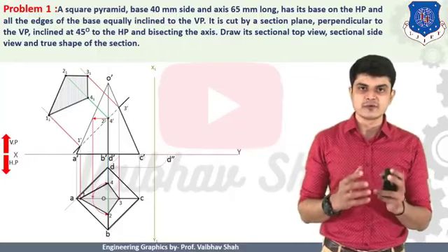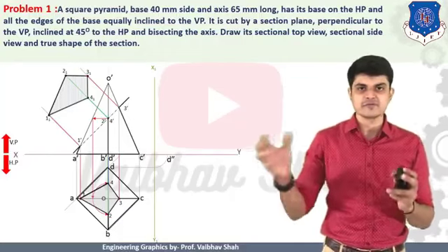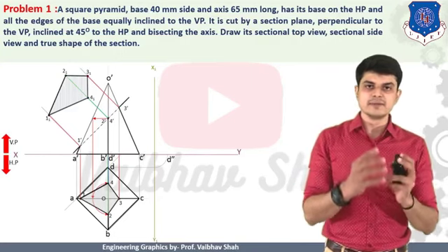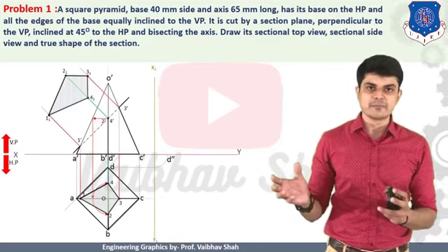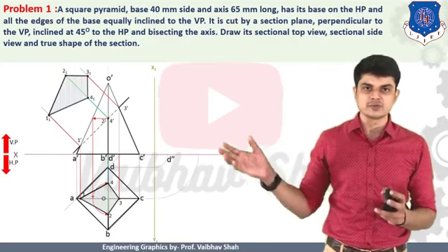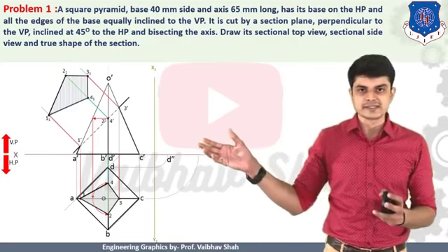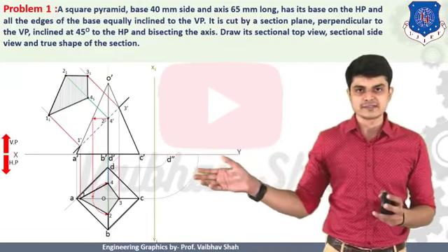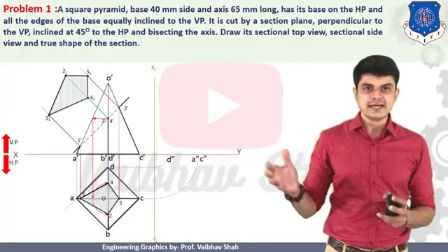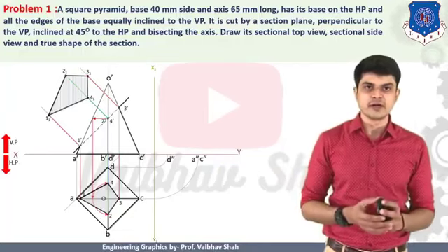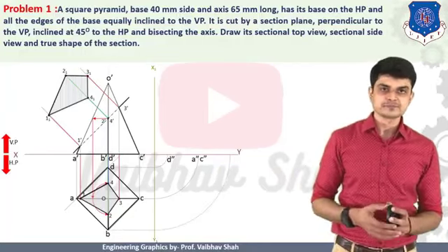So the intersection of the horizontal line of D dash and the arc of your point D will give you D double dash. Similarly, transfer each and every point to the first xy line. Then after, you should take the radius from the intersection of your axis to your point C, and then you should transfer point C. And then after, you should transfer each and every point onto your xy line like this.